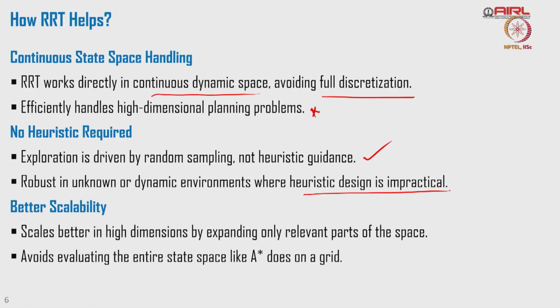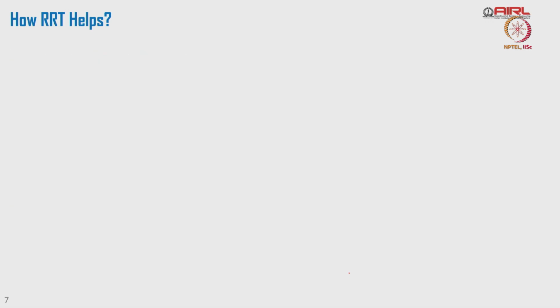And it is better for scalability. It scales better in high dimensions by expanding only relevant parts of the space. So, we do not need to consider the entire configuration space and then discretize it, that is not required. It avoids evaluating the entire state space like A-star.